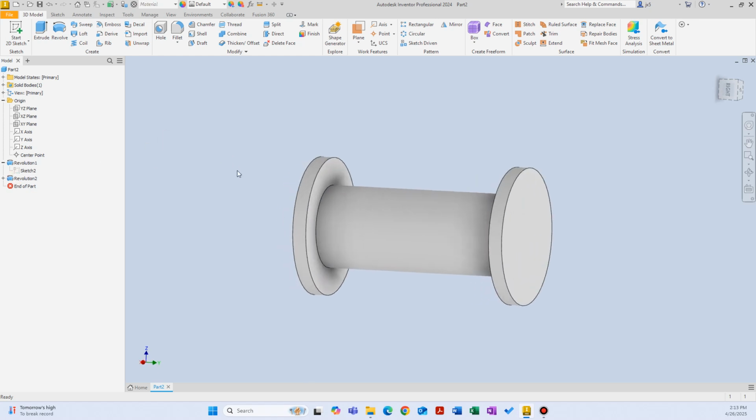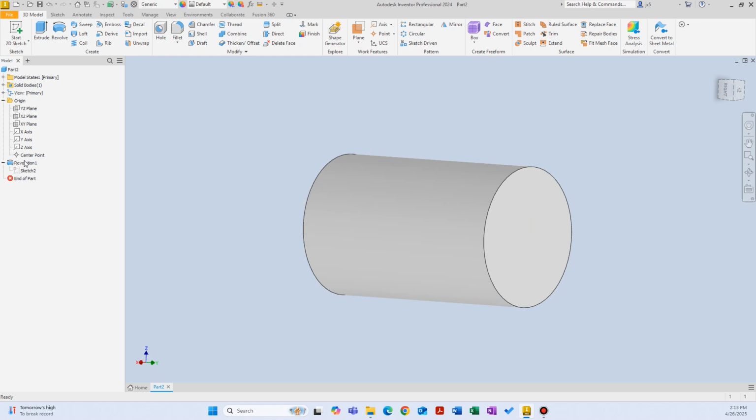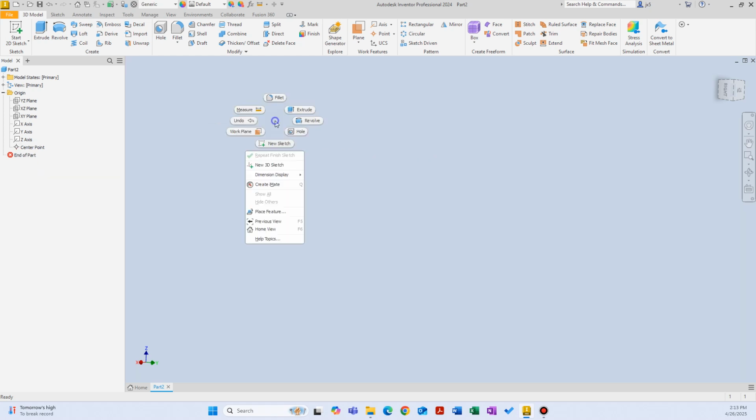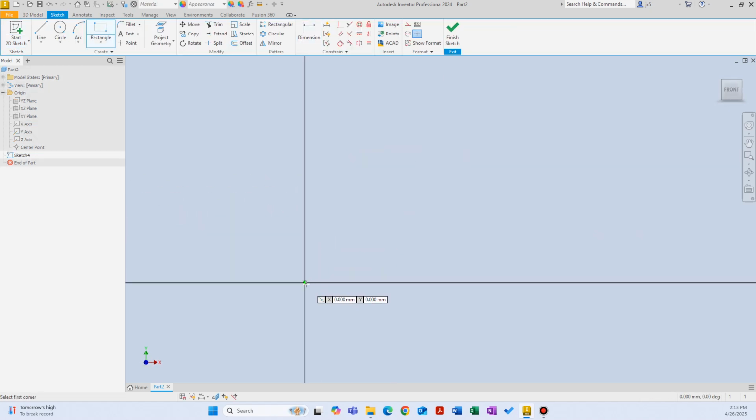But another detail that I want to talk about here is, every time so far we created two revolutions here, and these revolutions consume the sketches we generated. But every time we created a revolution, we took advantage of the y-axis or z-axis. We did not have to do that. You did not really have to select something that is titled as axes. You can actually select a line. So let's talk about that a little bit. Let's delete this revolution here, and let's delete this one as well. Now let's create a new sketch on the XY plane. Let's draw another 2-point rectangle and then finish the sketch.